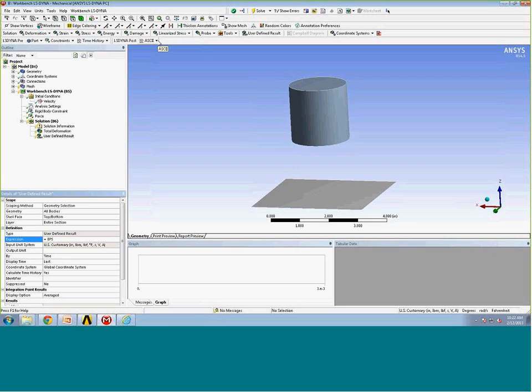I want to track energy data, and to do that, I go up to the menu near the top, and I can extract information from a variety of ASCII files that get written from the Dyna analysis. One of the most common ones to look at is this global data result file.